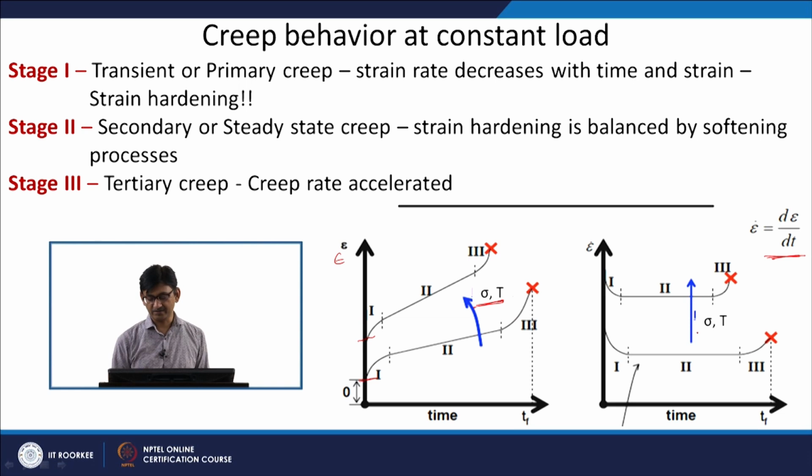Again you can see the effect of stress and temperature. At lower stress and temperature the strain rates will be lower, at high stress and temperature the strain rate will be higher, and the time to rupture will also be smaller.